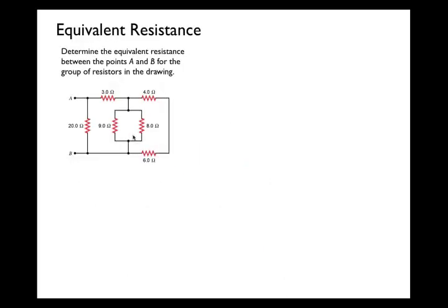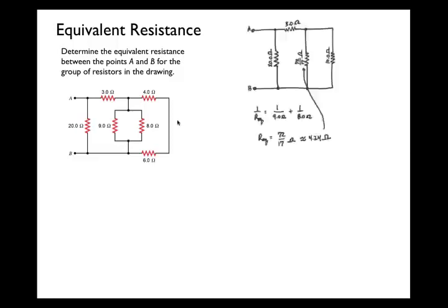All right, so I'm again on the hunt for series and parallel resistors within this that I can then sum. I can start a lot of places, but there is a 4 ohm resistor here that is in series with the 6 ohm, because if there were a current going through here, the same current would have to go through the 4 as goes through the 6 ohm. The 8 and 9 ohm resistors here are in parallel with one another because they have their opposite ends connected by conducting wire, so they'll have the same potential difference across them. Let's start by doing both of those things simultaneously.